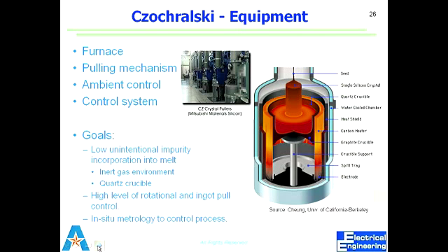What would happen if we have unintentional impurities in silicon? Well, it would have different conductivity properties than the ones you desire. So we will not know the electrical properties, the electronic properties. We wouldn't know if it makes it metallic. If it incorporates metallic atoms, then we have no gating effect. We can't control the band gap if we get those impurities in.